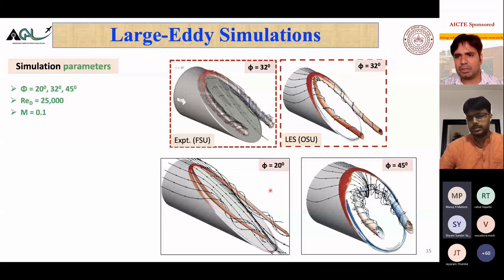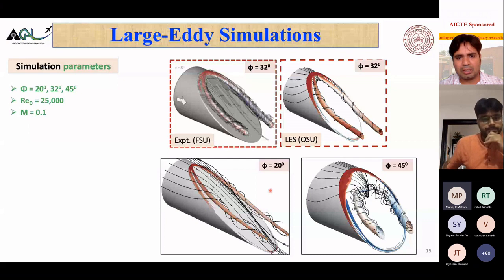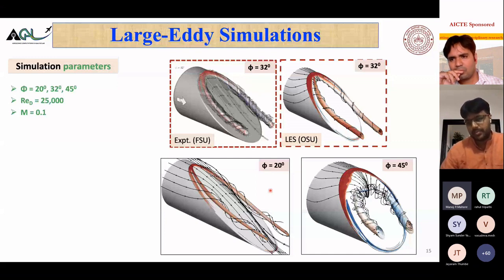Thank you. Dr. Rajesh, I want to ask one question. Is this vortex a horseshoe vortex? Can we call it a horseshoe vortex? Yes, these are separate from what you see on flat plates. This looks like a horseshoe vortex, and we actually name it a large horseshoe vortex kind of structure. But the lift-up kind of thing that happens on the flat plate is not happening here. This is just one big giant vortex sitting on the base flow. There are not several horseshoe kind of vortices.